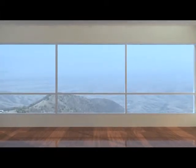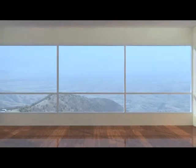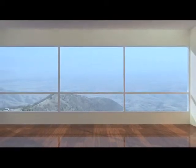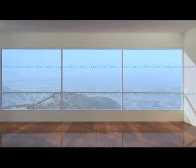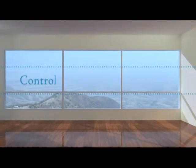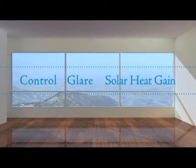If we think of daylighting as the design objective that offers occupants the most appropriate use of natural light in a particular space, the complexities of the overall task become clear. The three most significant challenges faced by the designer are control, glare, and solar heat gain.